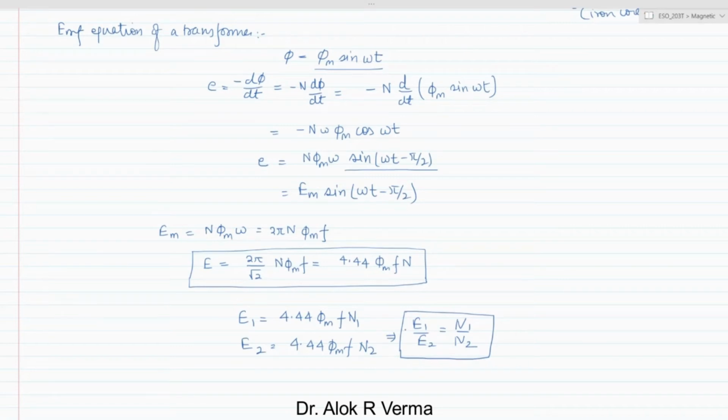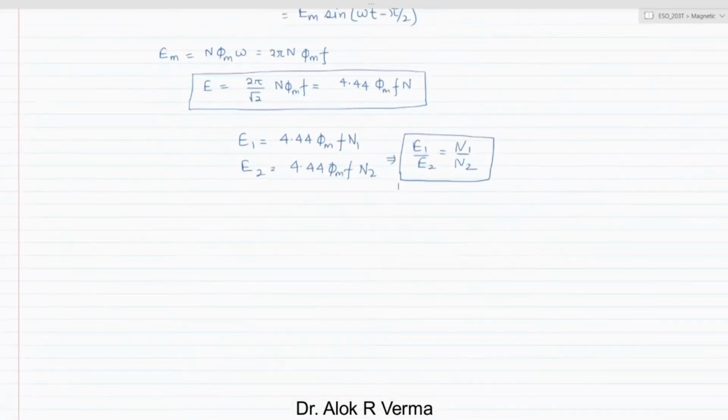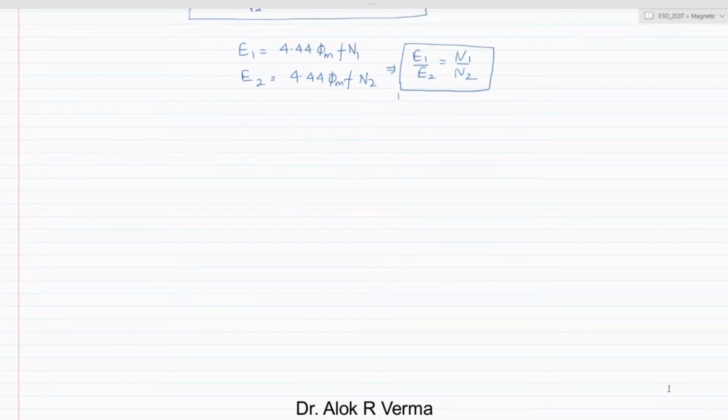So this is the voltage which is being given as a ratio of the turns of the mutual inductance, if k is given, from one winding to the other winding. So this N1 by N2 is known as the turns ratio.